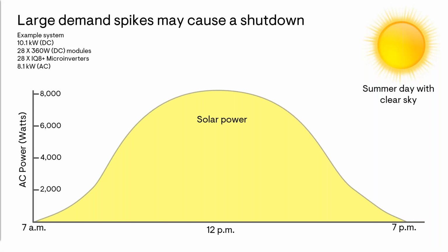While it's possible that a large solar system with a really attentive homeowner, who's paying attention to cloud cover and understands how much power their appliances demand, could potentially operate a large appliance with a sunlight backup system successfully, let's be real, most homeowners are not watching their system or the clouds like a hawk. For them to have a consistent, good quality experience with their system, it would be best to only back up relatively small loads like the loads that I mentioned earlier.